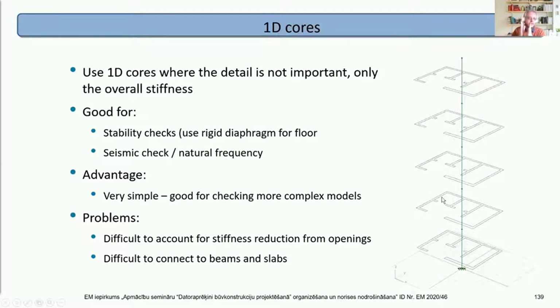So we might have a narrow bit of concrete in between and so on. Narrowing of the wall to give effective properties. Engineering choice. But it is a really simple, quick check type model that you can do. Good for designs, early concept stage, good for checking models.